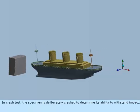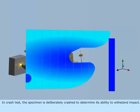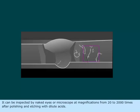In crash test, the specimen is deliberately crashed to determine its ability to withstand impact. Etch test involves inspecting the welded specimen for cracks. It can be inspected by naked eyes or microscope at magnification from 20 to 2000 times after polishing and etching with dilute acids.